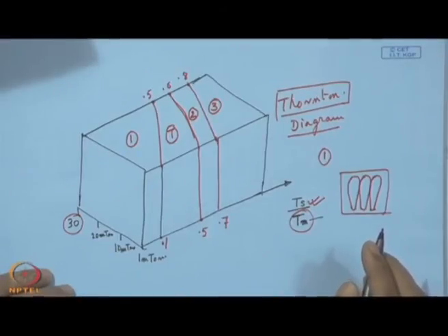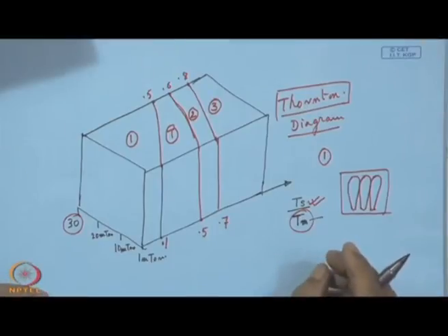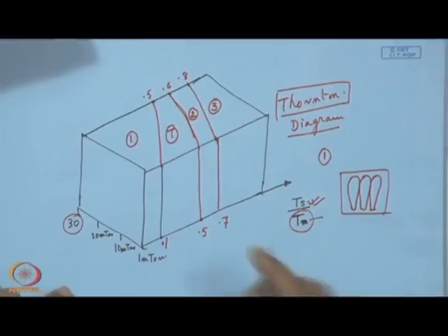But if we like to lower the substrate temperature, which is one of the significant points of sputtering, then if we like to have a deposition at low temperature, we must also reduce the process pressure here.